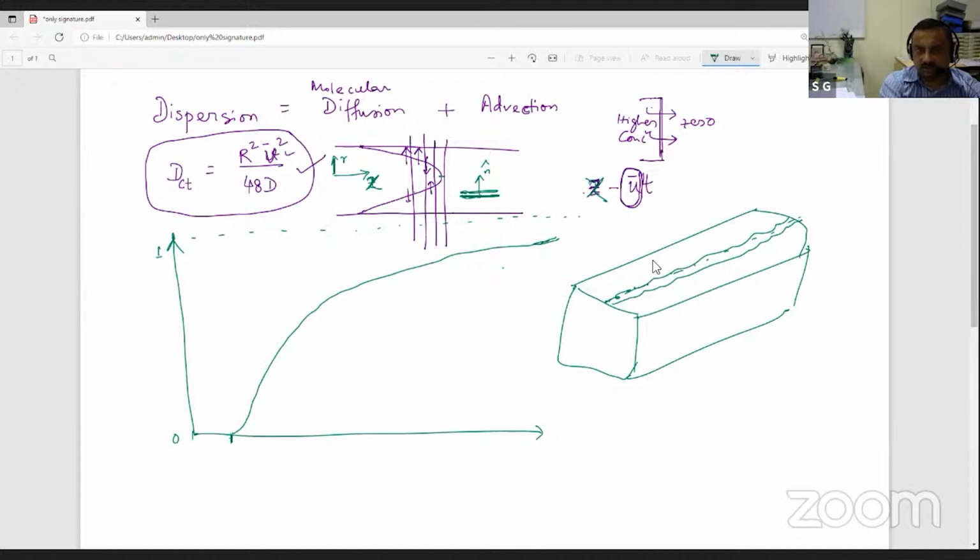No leak off means I'm not expecting any fluid to undergo any pressure driven flow in this direction. The fluid will travel through the fracture, and within a very short time the change of concentration will be reflected at the outlet. The moment it is reflected at the outlet, I will see the buildup of concentration. Only problem is, it will not reach 1.